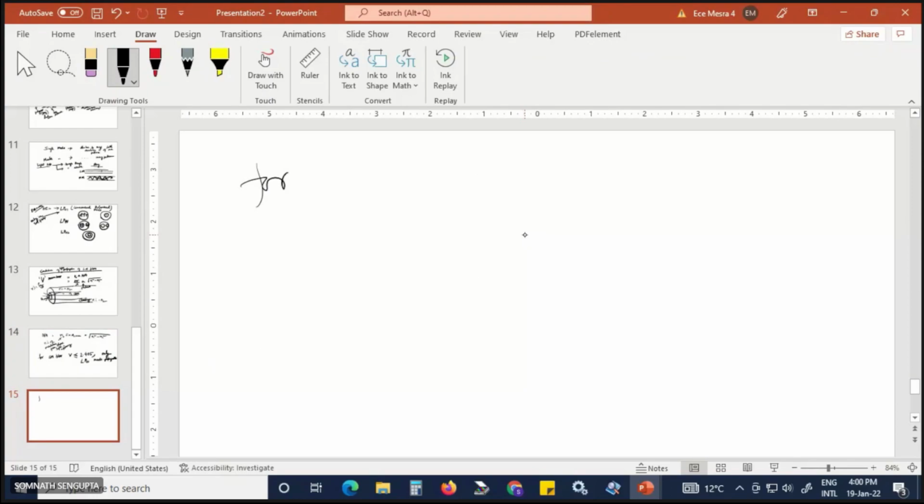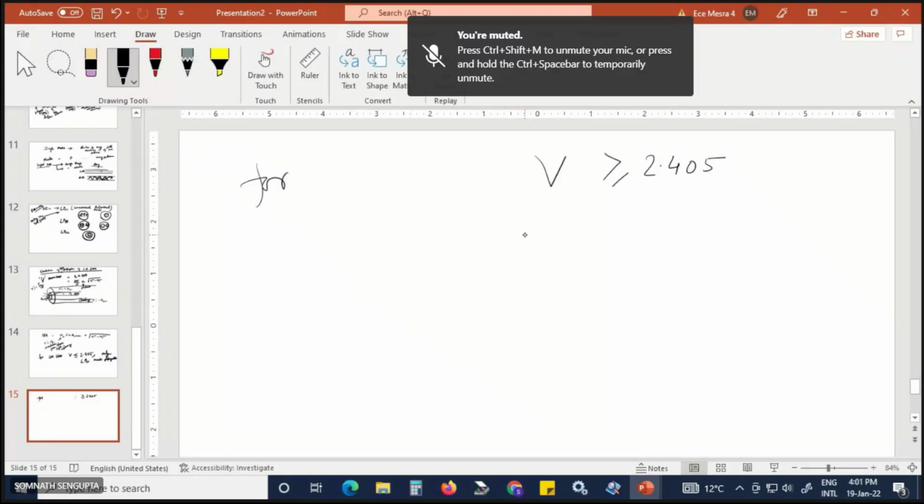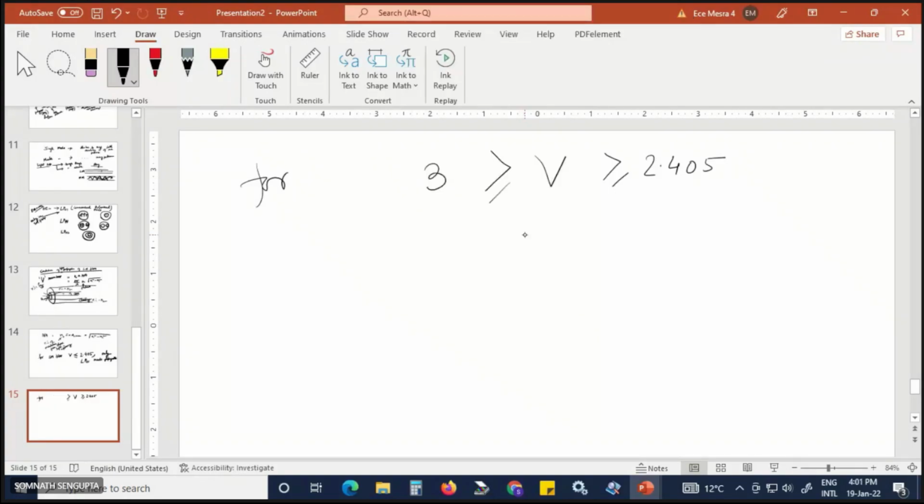For V number greater than 2.405 and less than 3.8, it propagates LP01 plus LP11.